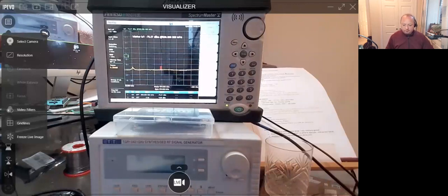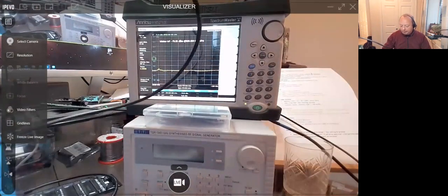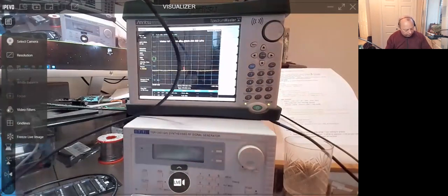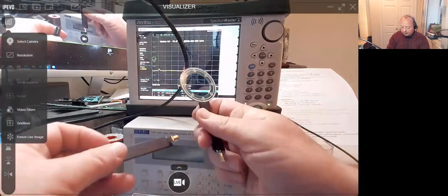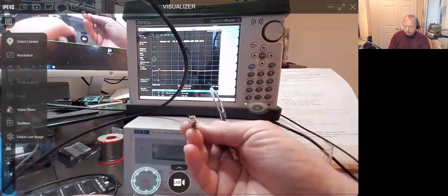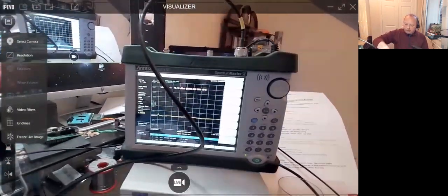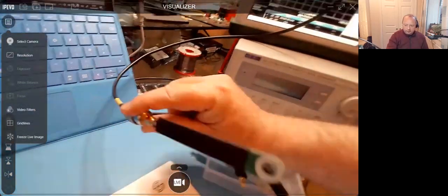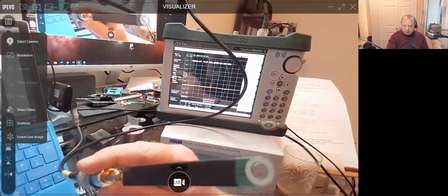So what we can do with this is, hopefully, I'm hoping this is going to work really well for us. I've got in here a number of different sized search coils, and these will work also with that cheaper analyzer. They're just PCBs with a bit of heat shrink and a small SMA connector. That's all it is, plugged into the top here. I've got just a cable coming off, goes around here and then plugs into here. And then I'm going to go around the board, and we'll do this in a second, and we'll see which parts of the Raspberry Pi are noisy.